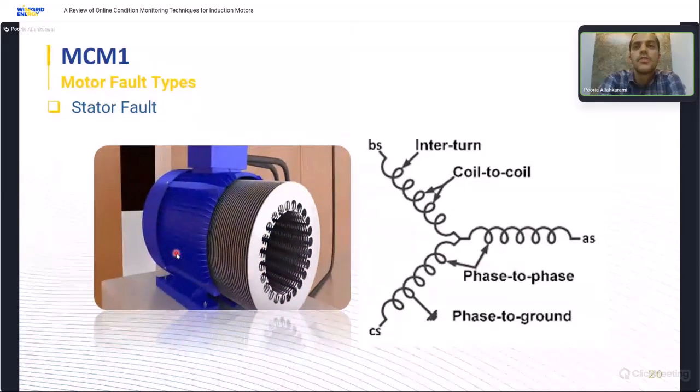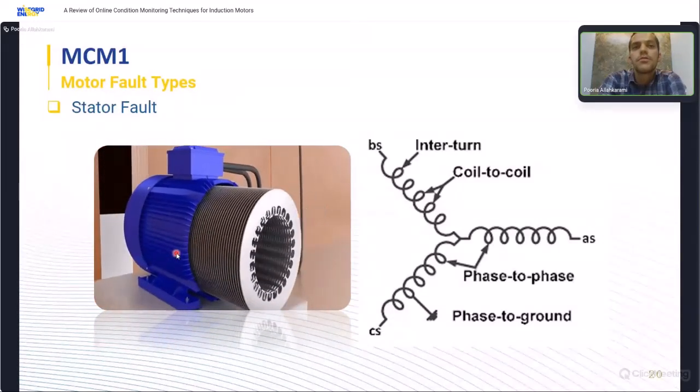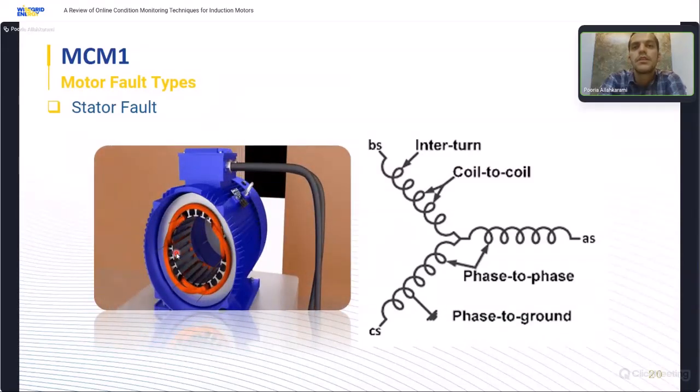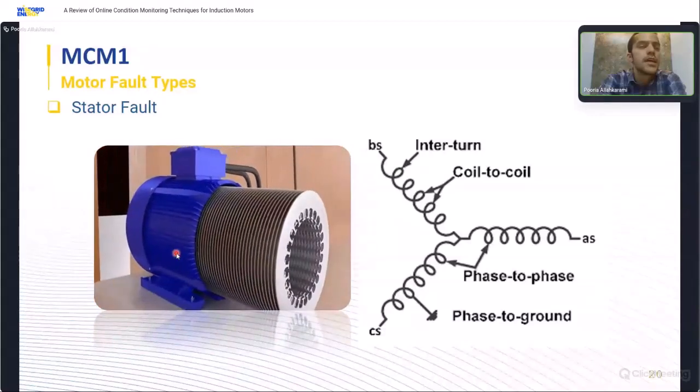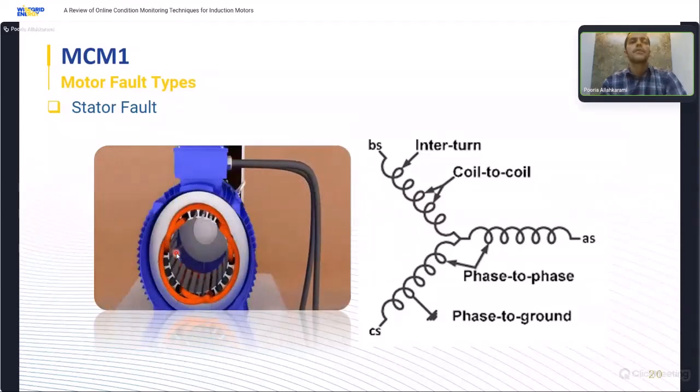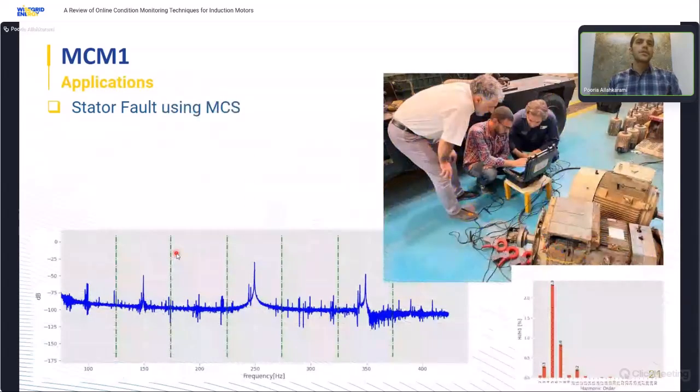When this fault occurs, a very high current typically flows through the windings, resulting in a complete burnout and severe damage to the winding. We need a full replacement of the winding, and this fault can be detected by the protection relay in the substation. But many faults can occur between the turns of the same coil. We call them turn-to-turn faults. In this case, the current increase is not so high that it can be detected by the upstream protection relay. But if we can detect them early, we can prevent the excessive temperature rise and avoid damage to the entire coil.